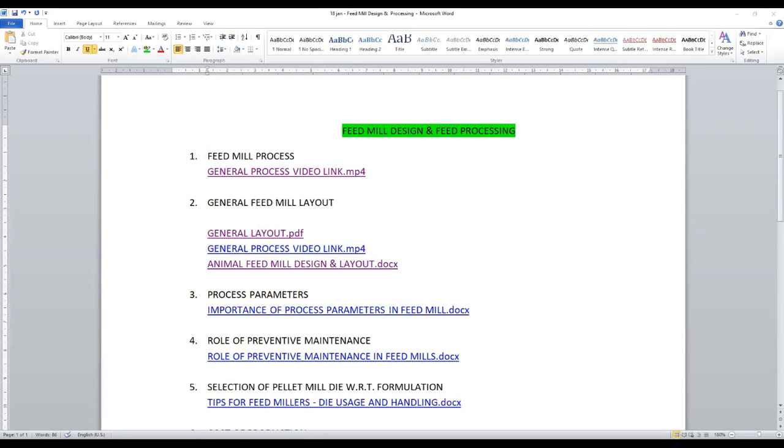Things to be kept in mind in feed mill design, like the weighbridge: the location of the weighbridge should give the vehicle its turning movement and be near the security gate, so that we can monitor the way. Even the weighbridge weight can be directly linked to the PLC and the inventory management module. For example, when a maize truck arrives and your inventory management module shows 4000 metric ton of maize, as soon as the weighbridge senses the truck and weighs it, it can be detected automatically and the addition goes to the inventory management module, and the daily consumption can be subtracted.